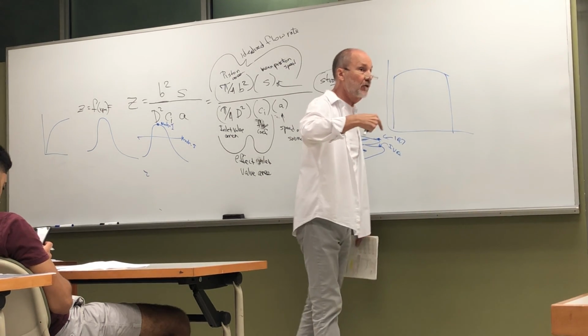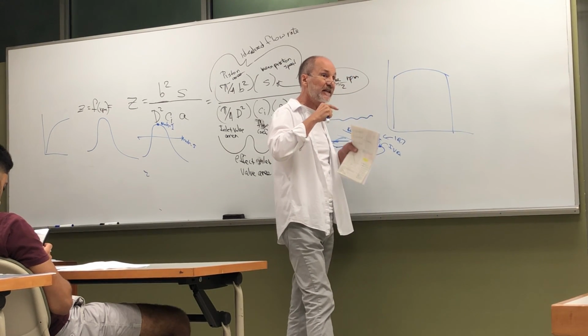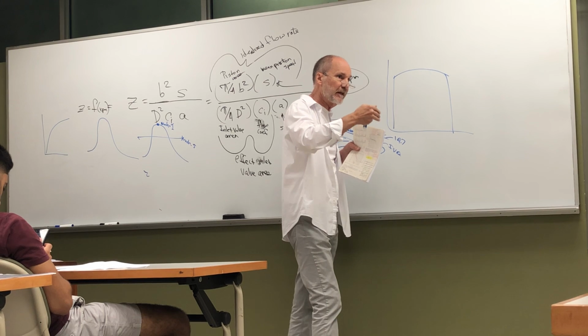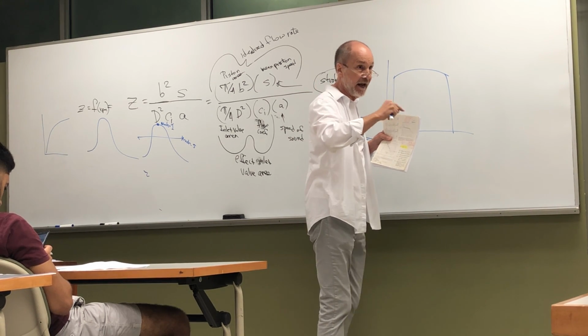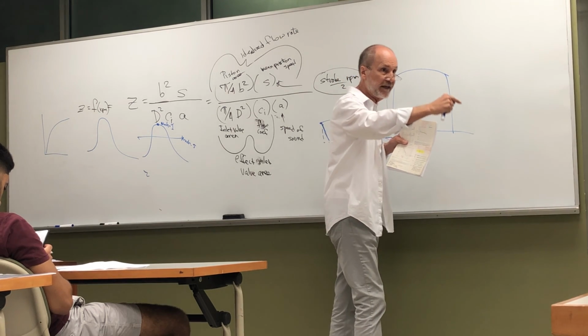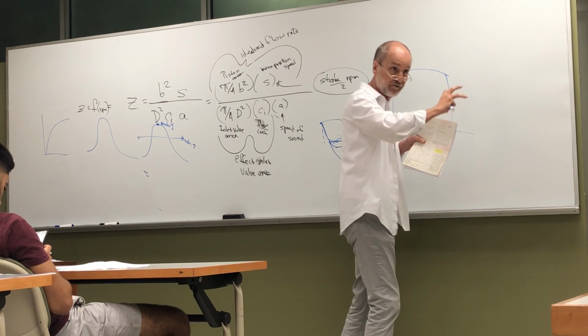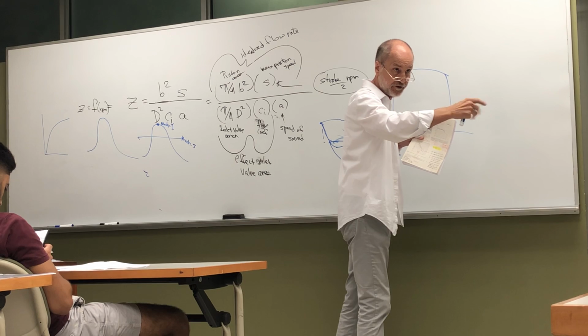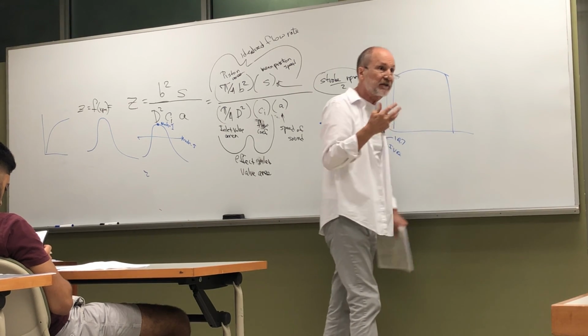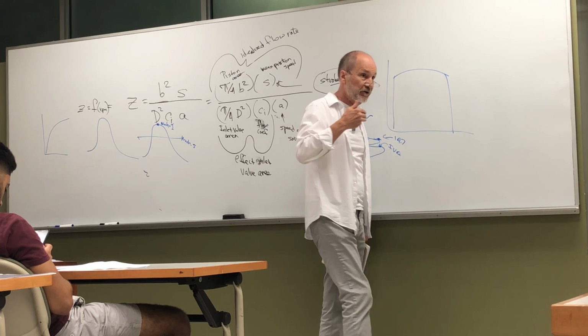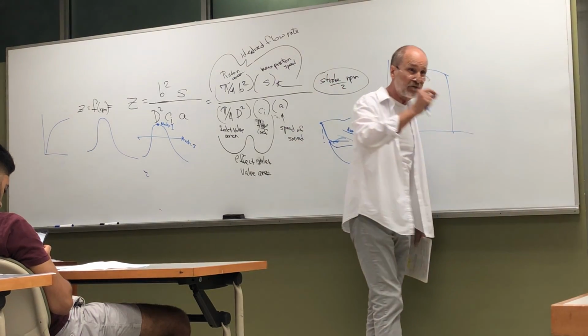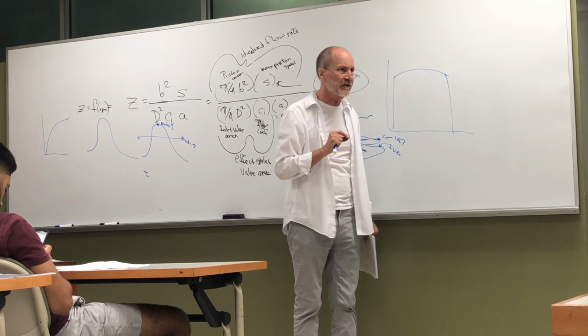So as you go faster and faster, the first thing that happens is you transition from laminar to turbulent, and you get relatively big eddies. Then as you go faster and faster, those big eddies break into smaller eddies. You still have the larger eddies to a certain degree, but you have to dissipate more and more energy, and you need more and more eddies to do that. By the time you hit sonic, you've got extremely small scale eddies.